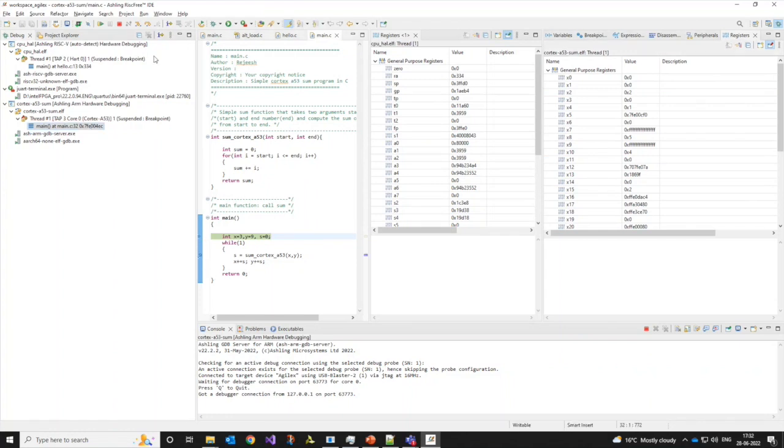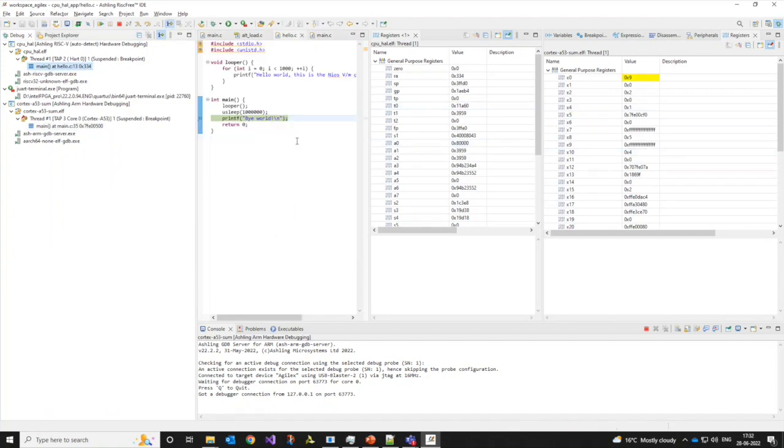Maybe I can put a breakpoint over here. I just run the ARM, and I can see the ARM registers being updated. Nios V is still there, and actually this program has exited now. Maybe I'll put a breakpoint and run here. You can see the Nios V registers getting updated. So like this, we can compare the registers, and again stressing, it is not just registers. For any debug view, we can use this pin and clone feature, and then we can compare the values.